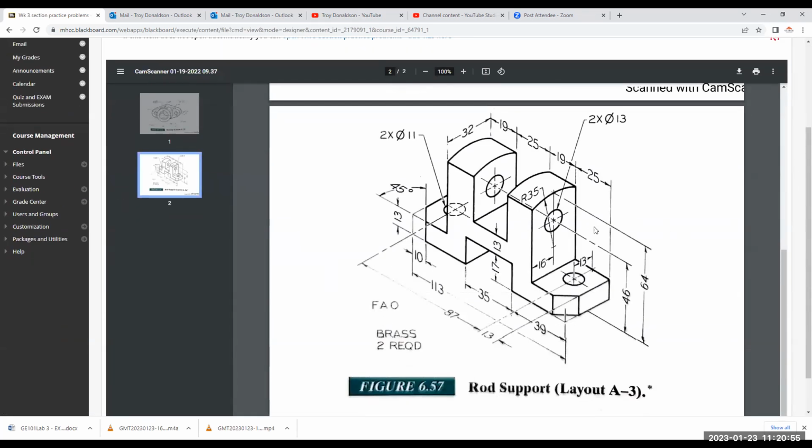All right, any questions on this one? I think it's all pretty straightforward. I don't see any tolerances. Just be careful on where the dimensions come from. This comes from a false corner right here. That's all supposed to be straight, but it's coming from right there, and that corner actually doesn't exist, right? So just be careful where the dimensions come from. Try to look carefully at that.